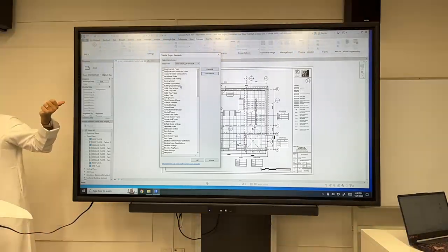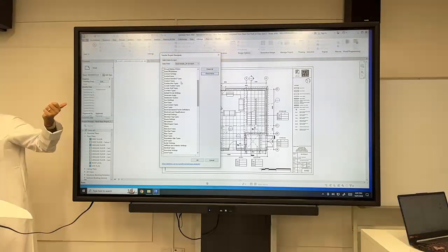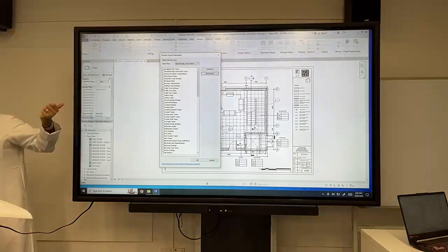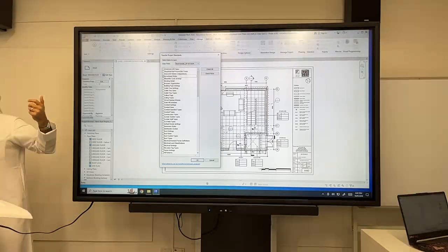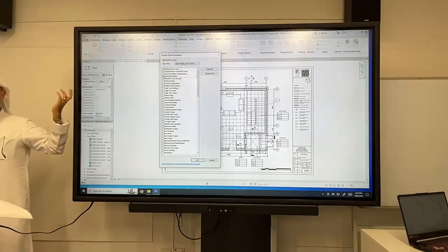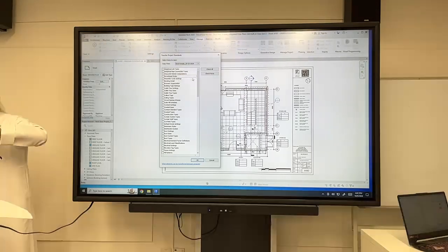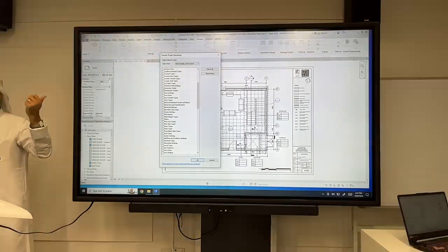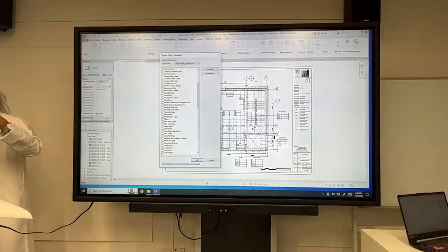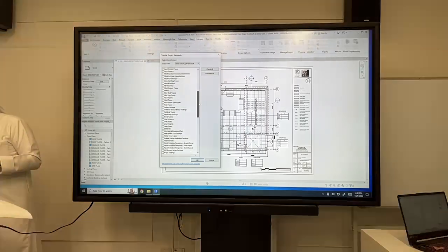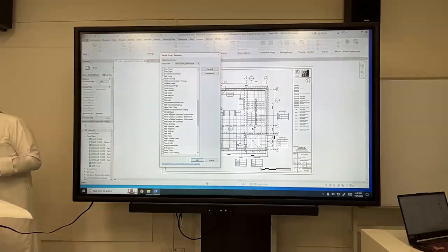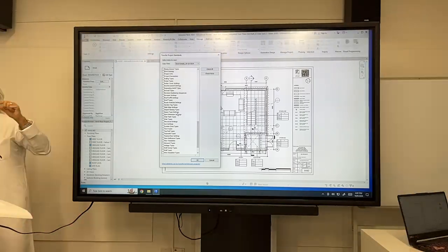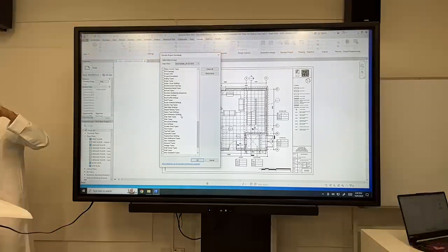All these things are things you can check to transfer. So look at arrowhead styles. Let's say you changed an arrowhead, the style of it. That will bring it over. Dimension styles. We added metric, the millimeters. That would transfer it over if you had file to file. Object styles, line styles, you've got different line patterns, fill patterns, things of that sort.